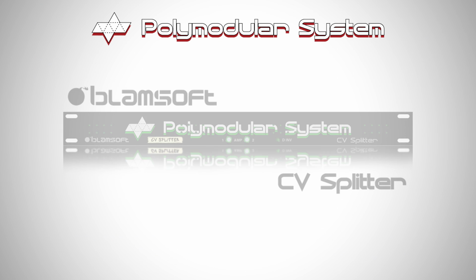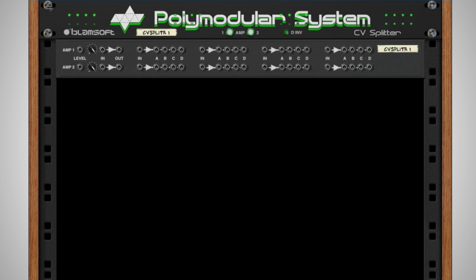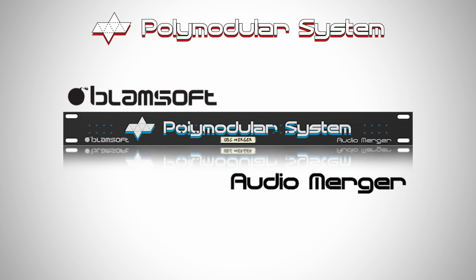CV Splitter. CV Splitter provides 8 channels of CV splitting with 4 outputs for each splitter. It also has 2 voltage-controlled amplifiers like the CV merger. The LEDs on the front show the level of the CV outputs. The D-inverted button controls whether the D output is normal or inverted, which changes a positive signal to a negative signal and vice versa.